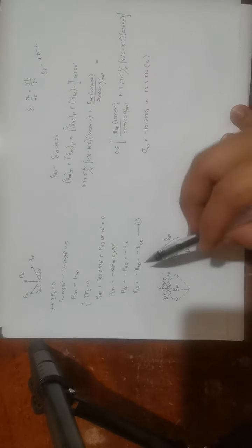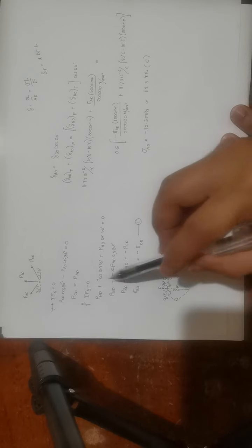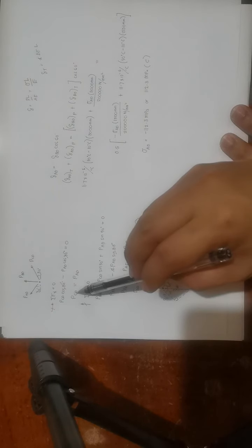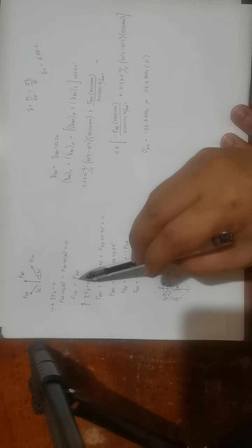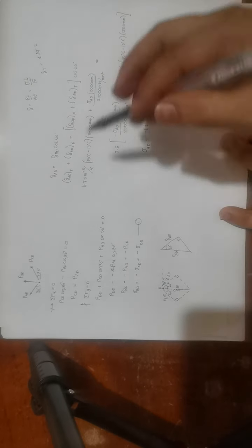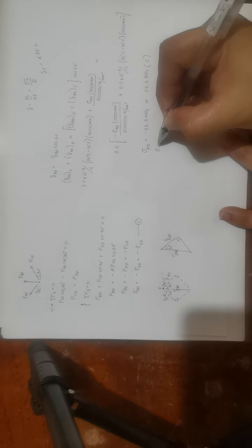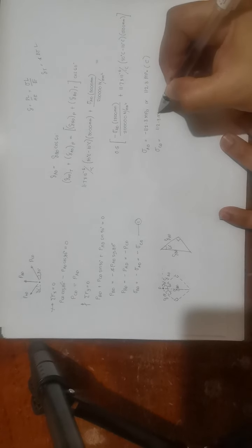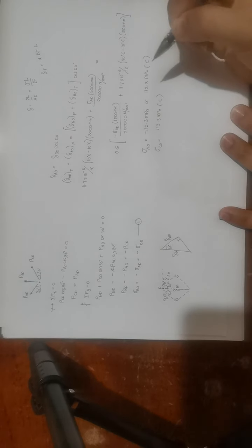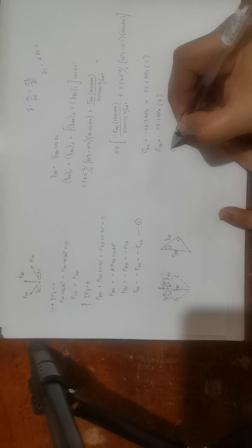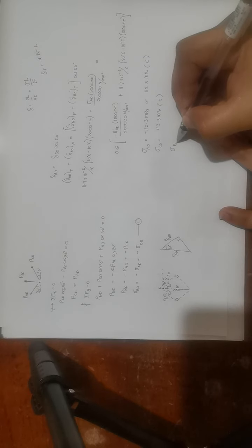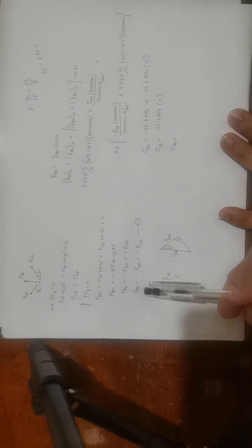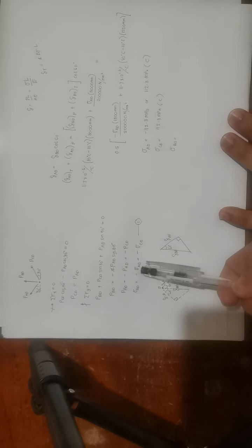So since yung ating force or actual load in member CD is equivalent to the actual load in member AD, yung ating stress in CD is also equivalent to 112.3 megapascal. So our stress of member BD, using this relationship, stress in member BD is negative stress of member AD.